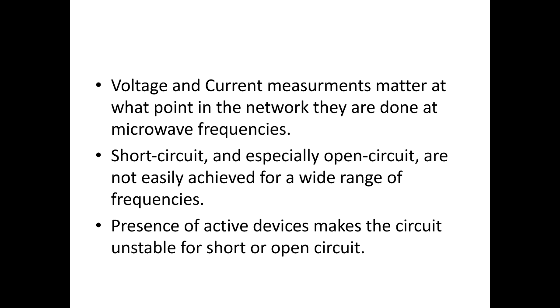Short circuits and open circuits are not easily generated at microwave frequencies, because, as we have studied in transmission lines, to obtain a short circuit or an open circuit, not just the load impedance, an appropriate length of transmission line also has to be accurately measured and be a part of the system. Also, this length is dependent on the frequency. So getting the short circuit and open circuit conditions is difficult. Short circuit and open circuit conditions are what were used to calculate the Z parameters. Hence, Z parameters and Y parameters cannot be easily applied to microwave frequencies.